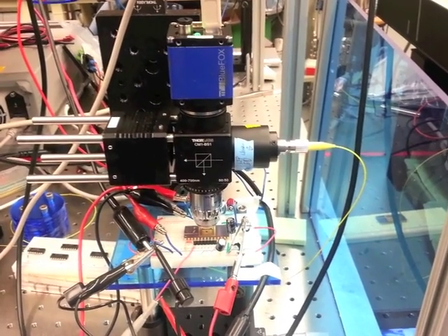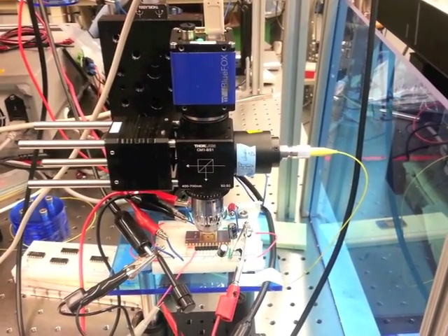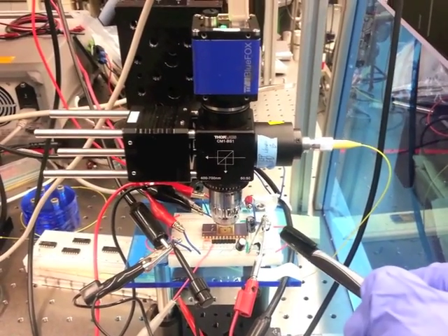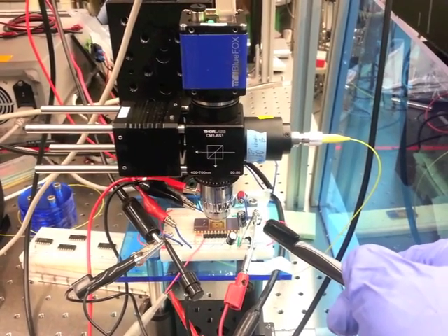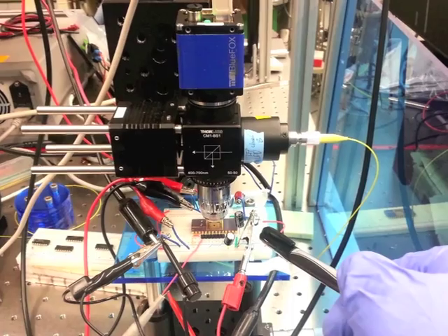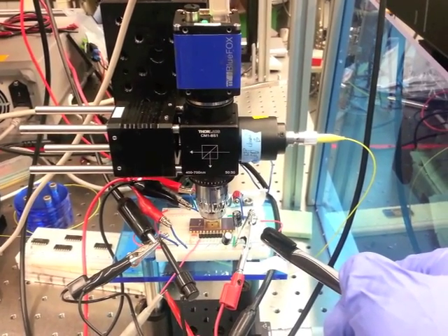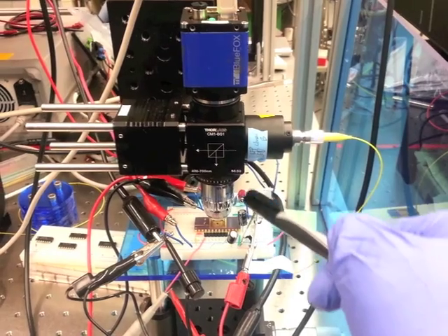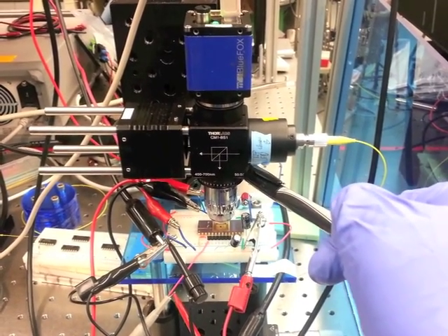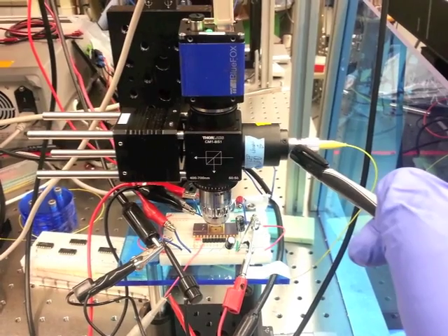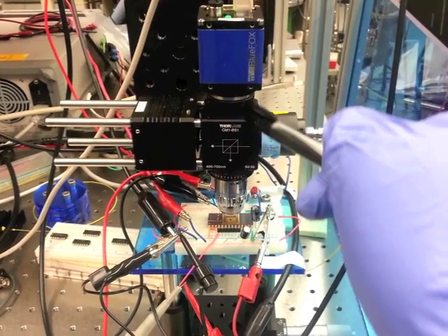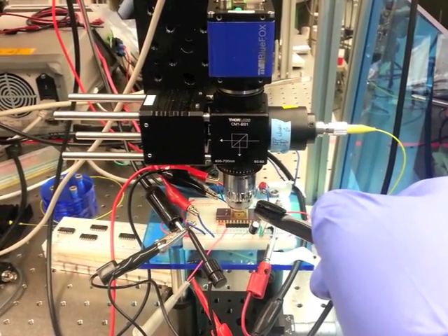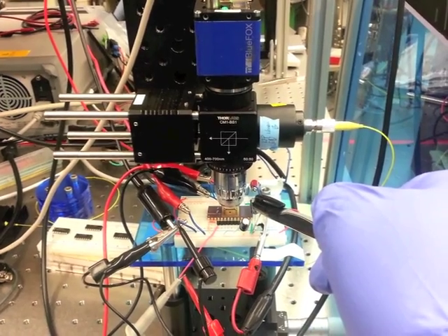Shown here is our photodetector chip test bench. The photodetector IC is placed into a breadboard, which is in turn mounted on a precision XYZ stage. This allows us fine manipulation of the individual photodetectors underneath laser illumination. The optics setup shown here above the die consists of a beam splitter that accepts laser illumination from a diode laser shown on the right and relays this illumination to a camera for imaging and to the individual photodetectors for probing.